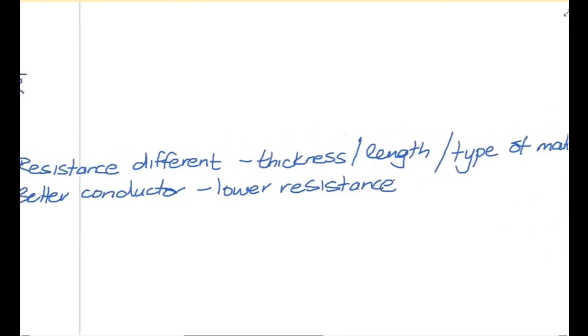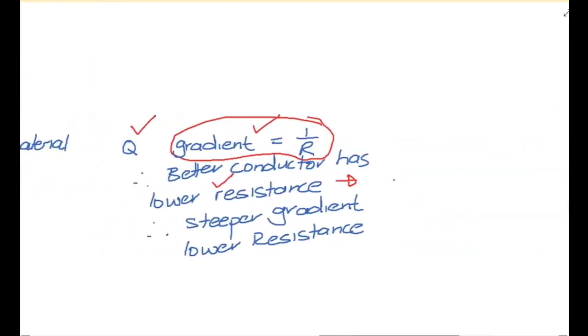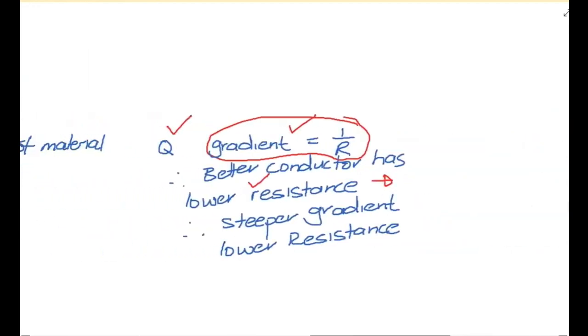Hopefully, all of you at this point have got some idea of being very careful when you're looking at Ohm's law. If it's V on the Y and I on the X, that's a win, because it means I can just go with V over I. But if it is I versus V, then I have to consider the fact that my gradient is 1 over R. Okay, so there we go.